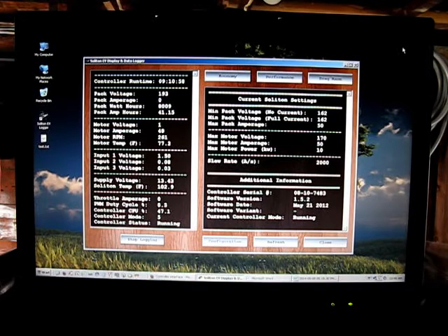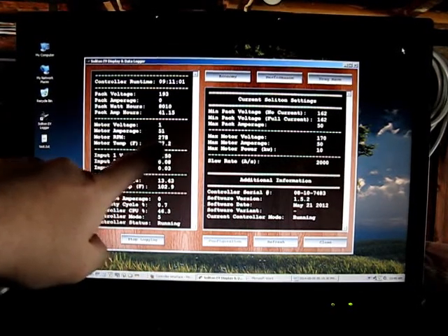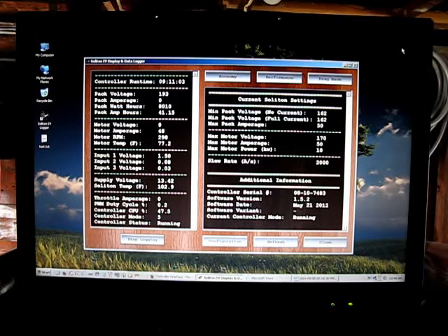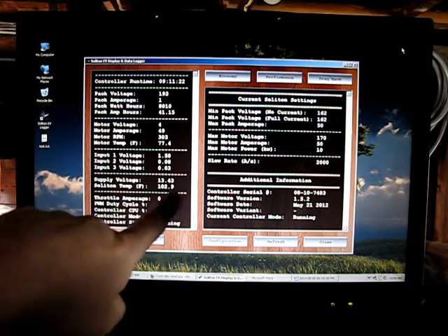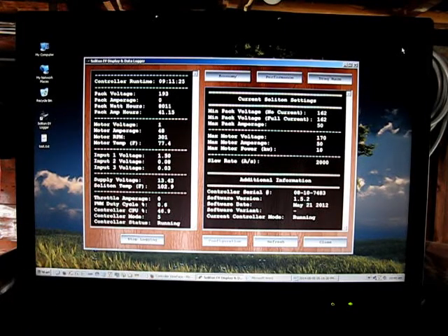But anyway, so now you can see we're at 270 RPMs, 50 amps at between 0 and, I think I saw, 8 volts on the motor. So something's going on. Not really sure what. I thought maybe the Soliton might have hit a thermal limit, because there is no airflow on it, but it's at 102 degrees Fahrenheit, which is not really all that hot, and it's not even hot enough for the internal Soliton fans to kick on at this point. So it's like, okay, it's really not that hot.